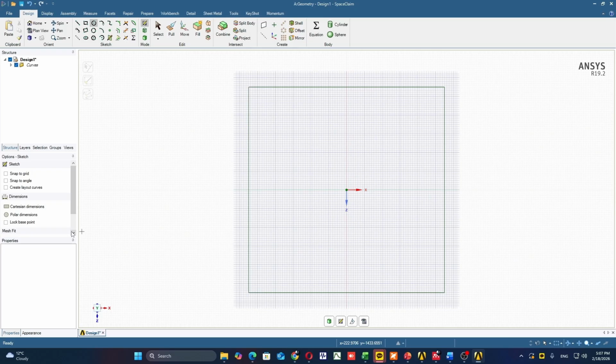So we'll have a total of 16 bolt holes. To do this, we'll have to select the Cartesian dimension first, and let's select the corner, and the bolt will start 50 mm from the x-axis, and also 50 mm from the z-axis. So write minus 50, tab, plus 50. Yeah, so the dimension will start from there.